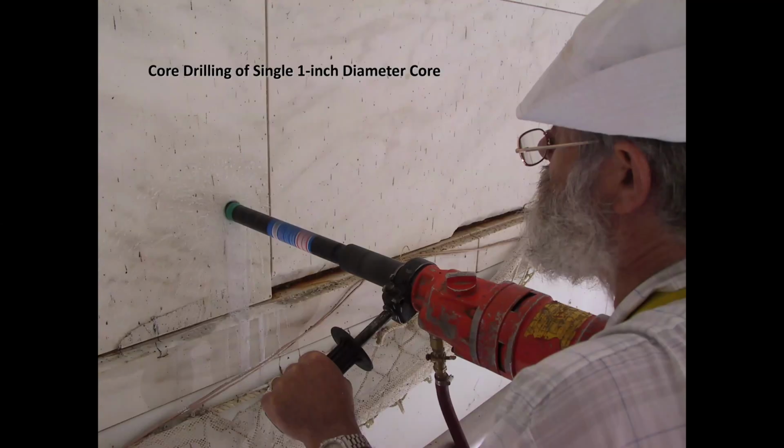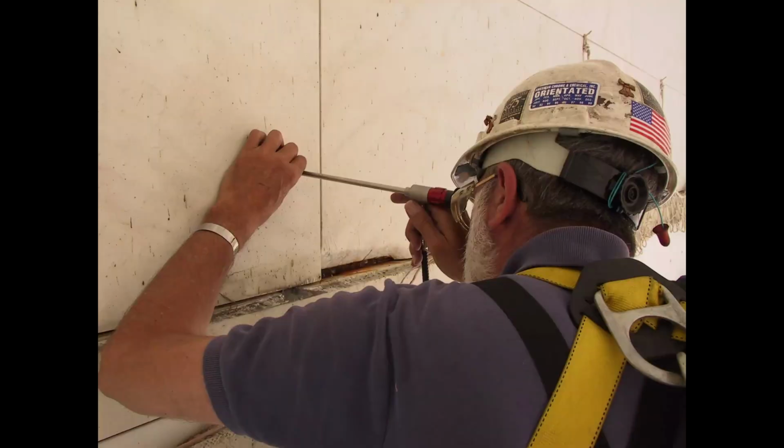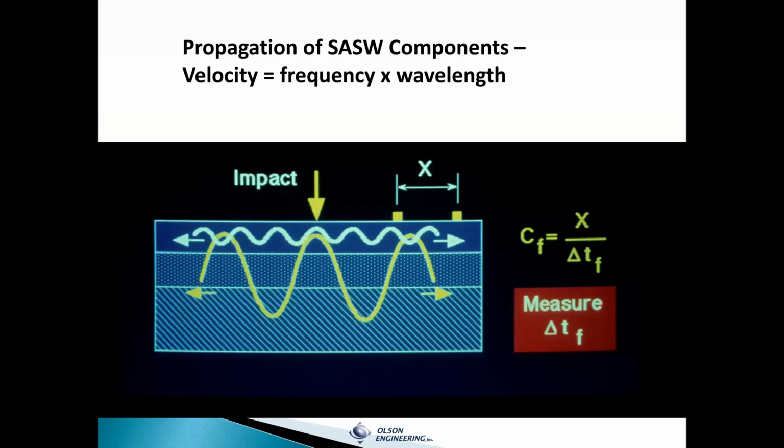They let us drill one single 1-inch diameter core for calibration purposes of our investigation. That's unusual. You normally don't get to touch historic masonry much at all. So with that, we did some borescope work to take a look inside. We really didn't see much of interest.